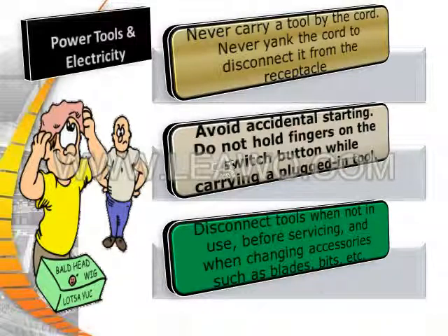Never carry a tool by the cord. Never yank the cord to disconnect it from the receptacle. Avoid accidental starting. Do not hold fingers on the switch button while carrying a plugged-in tool. Disconnect tools when not in use, before servicing, and when changing accessories such as blades, bits, etc.